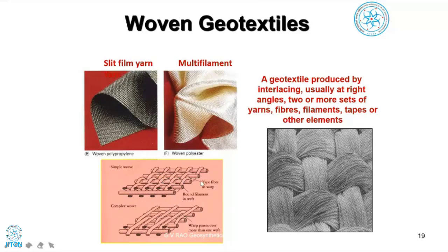Even before we go further into this, we will also see more details. At intersections, it is possible to have some openings. Otherwise there are no openings. There are micro openings here, but that doesn't mean it is sealed. The filaments are simply twisted together to make a yarn. And at the intersections there will definitely be some small openings. This is what we have to remember. And then obviously we can think of having such close packing also. That means here both the yarns are put together very closely. If it's a net-like kind of thing, they may not be so close together. That we will see.